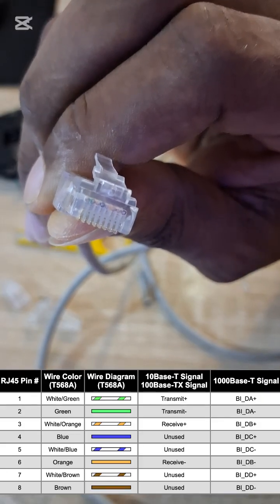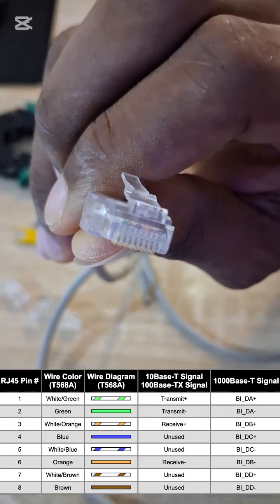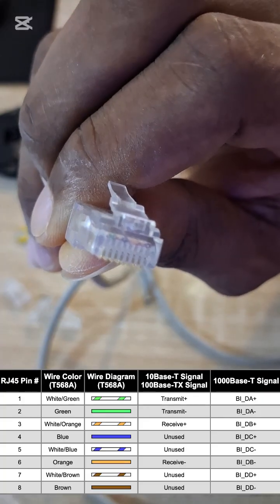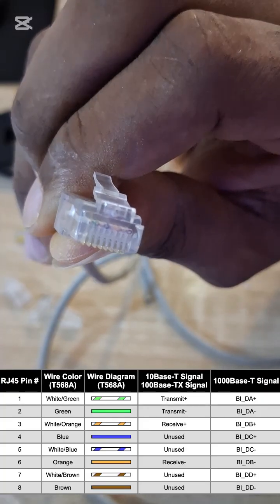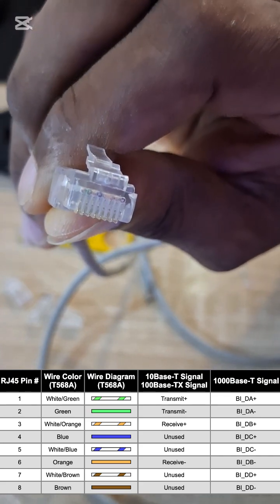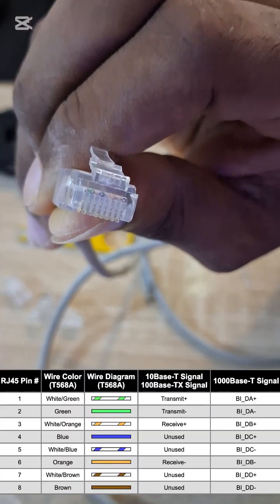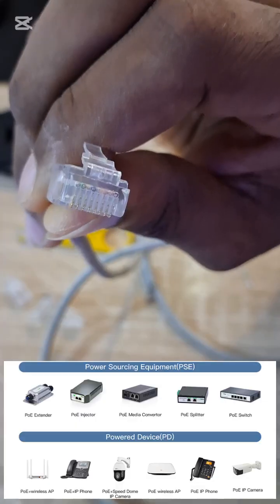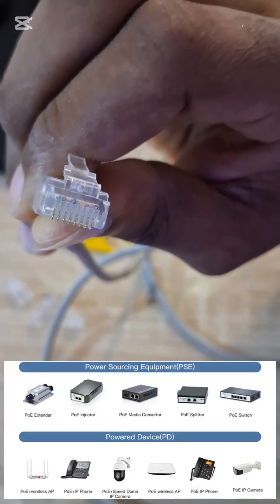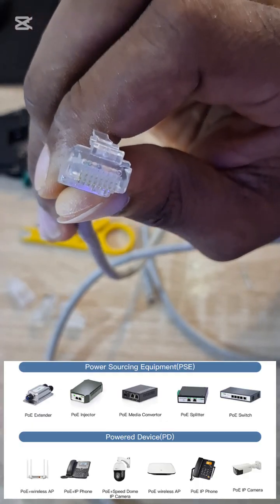So normally if I cut off pins 4, 5, 7 and 8, I should still be able to transmit data with my cable. I'm not going to cut them off in this video, but I'm saying that if you cut them off, you can still transmit data with the cable. The only time pins 4, 5, 7 and 8 are functional is if you have a PoE device. PoE means power over Ethernet. So if you have an access point or an IP camera that you want to power using this cable, then that is where those pins are relevant.